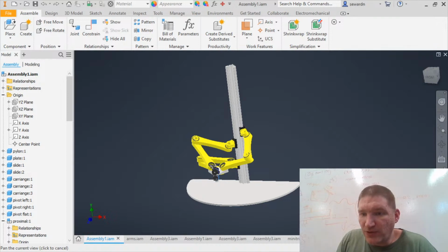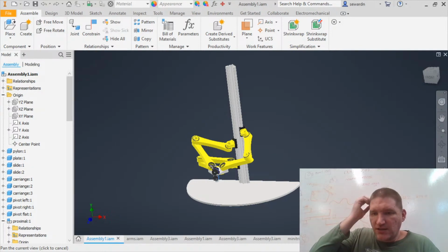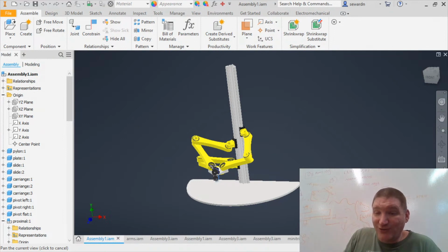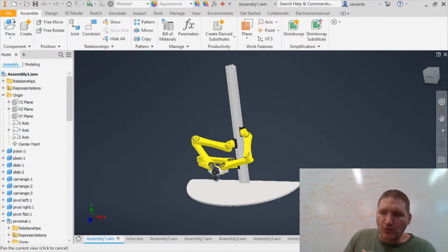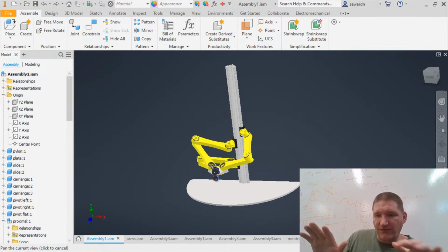How long a monorail would I need for like a 300 millimeter build volume? Okay, so the monorail as drawn, you need about 500 millimeters on top of whatever width you want. So if you want to build something 300 millimeters tall, you need an 800 millimeter rail. That's just a rough rule of thumb. It depends on how big you want your Y and all that good stuff. But for the way I have it drawn, I need 500 extra millimeters for however wide I want.